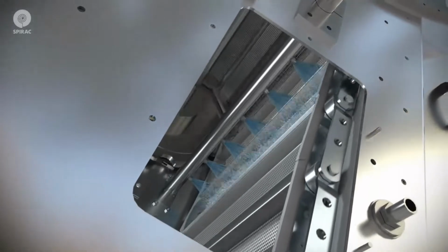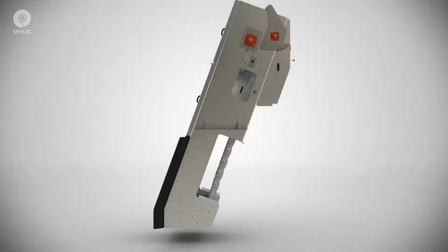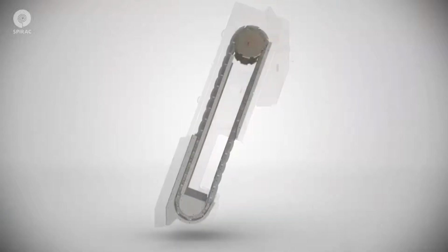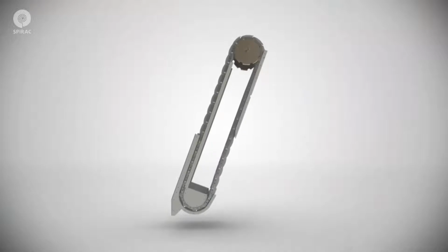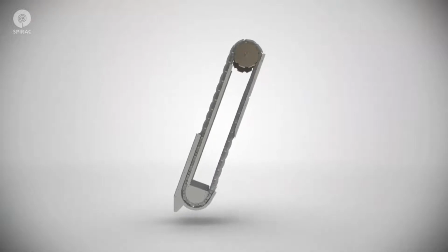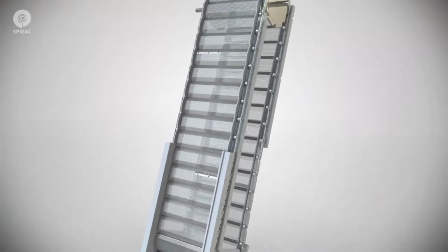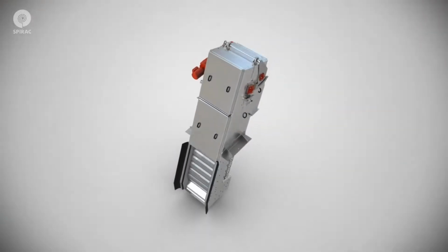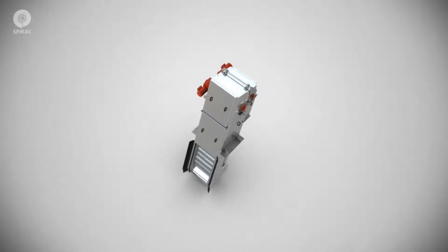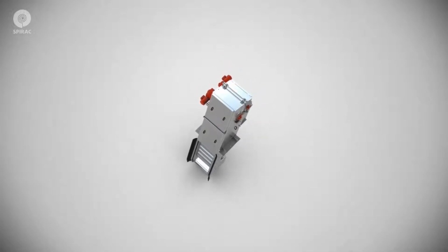And then there's a spray bar behind, which also washes the debris off the back of the panel into the discharge chute, which would then feed into a screenings handling unit. All the chain runs in an ultra high molecular polyethylene chain guide, and the chain is stainless steel or mild steel, or can be duplex depending upon the application, as is the construction of the screen itself.